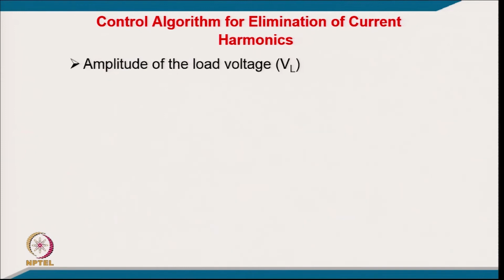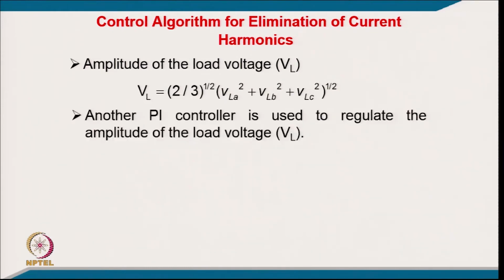And now coming to the amplitude of the load voltage, we are already measuring the 2 line voltages, and from them we get the 3-phase load voltages, and from which we are calculating this amplitude of the load voltage by using this expression.